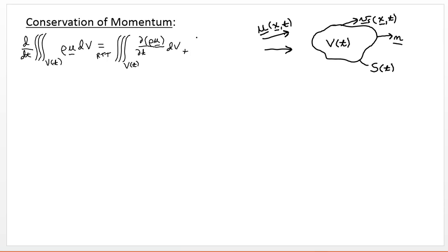And so this part will be the surface integral over the surface area S(t) of n dotted with v_s, multiplied now by the momentum density rho u, dS. That's simply an application of the generalized Reynolds transport theorem for a non-material control volume that has surface velocity v_s. That's where the surface term comes in here, and the Reynolds transport theorem is also known as the Leibniz rule, as we said.